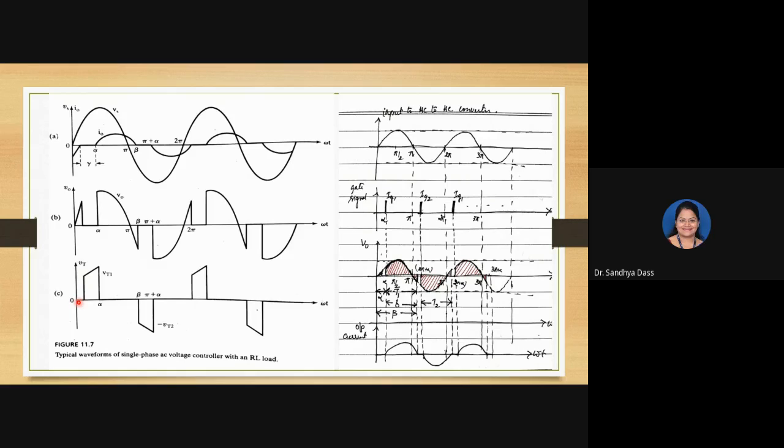So initially, let's start from here. When the device is not turned on, the voltage across T1, as you can see, follows the input. Now you should be able to relate that, and give the understanding of the working of the power devices. So the voltage is the same as the input you have applied. Once the device is turned on, the voltage across it will be minimum. That is shown here as 0 when it is conducting.